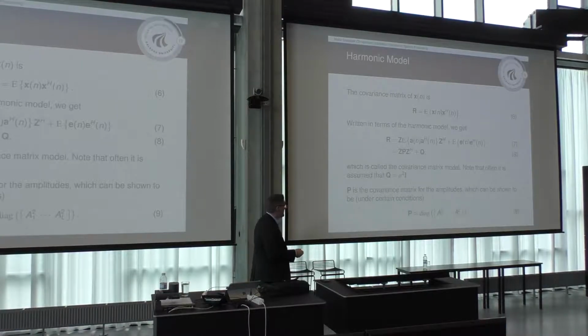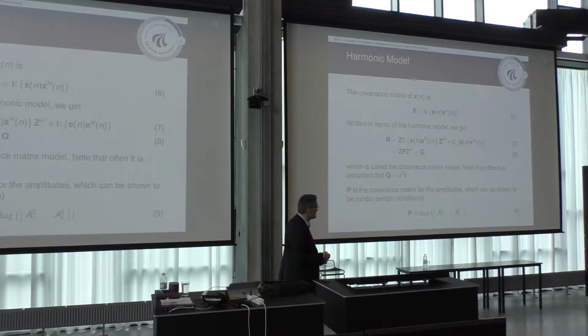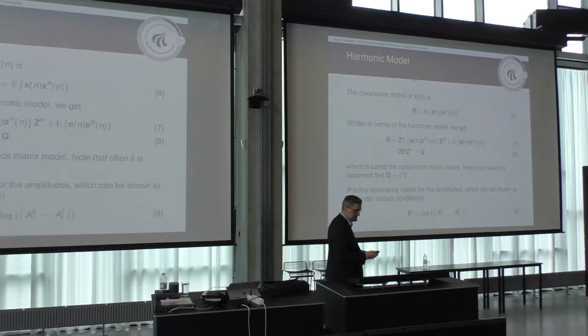And this is an example of what I mentioned before with the sufficient conditions, because this model actually came from array signal processing, and particularly from literature on narrowband array signal processing. And the assumptions they make there to end up with this model, it's not exactly clear how this applies to something like time series analysis. But you can actually work this model out so that even if you assume the signals are deterministic and you compute a sample covariance matrix, you end up with the same result. So that's another example of the sufficiency of these conditions.